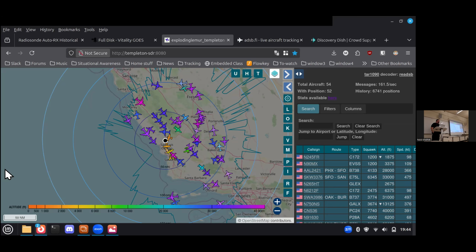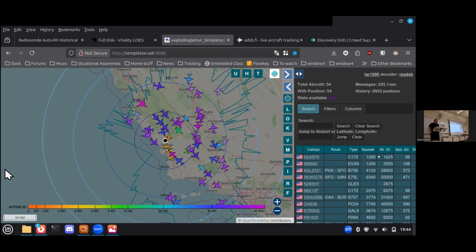With a separate antenna, I would need a lot of separation, probably vertical, so that I didn't blow out the front ends of all my SDRs. The RTL dongles have basically no selectivity, so if you have a strong signal, that's what you're receiving no matter where you're tuned.